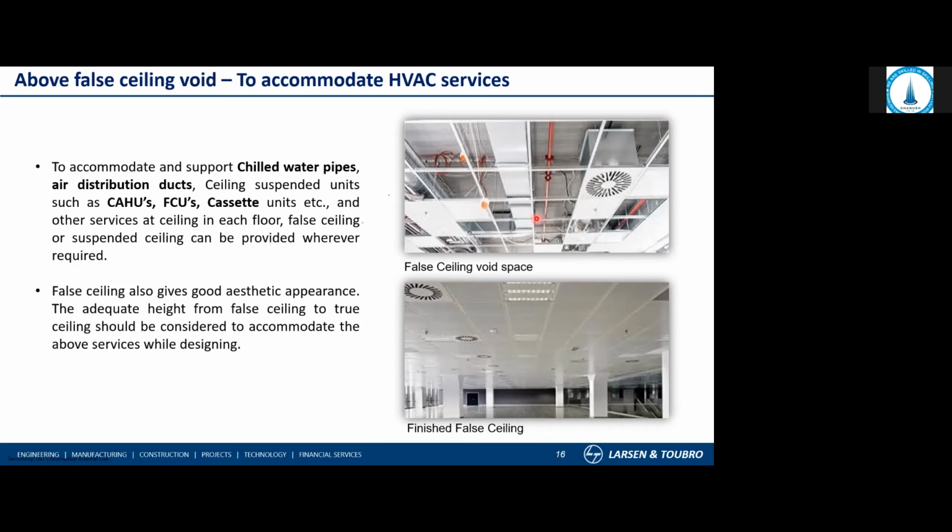Normally we consider that it will be either a gypsum false ceiling, a metal false ceiling, or a grid type gypsum false ceiling. For the gypsum false ceiling, we consider 12 to 20 mm thickness, but we normally ignore the support behind that gypsum false ceiling.